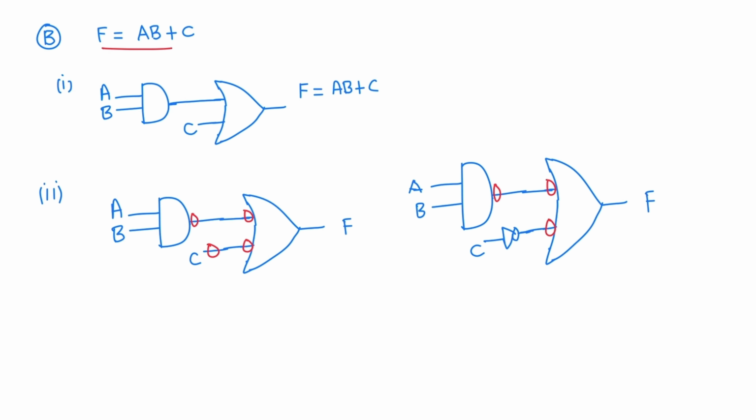It can be implemented by using one 2-input AND gate and one 2-input OR gate. So this AND-OR gate is converted to NAND logic. Add bubbles on the output of the AND gate and the input of the OR gate. So like this, represented in figure 2. So we will get figure 3.